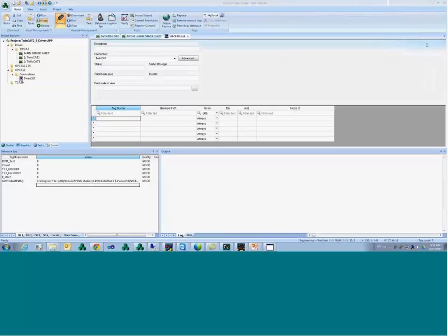So the question is: is there a way to import variables from Beckhoff with a two-dimensional array? Basically, no, because we don't have multiple dimensions. We import the variables, of course, but we don't create them in our tag database as two-dimensional arrays. You're going to create multiple tags with one dimension. Okay?